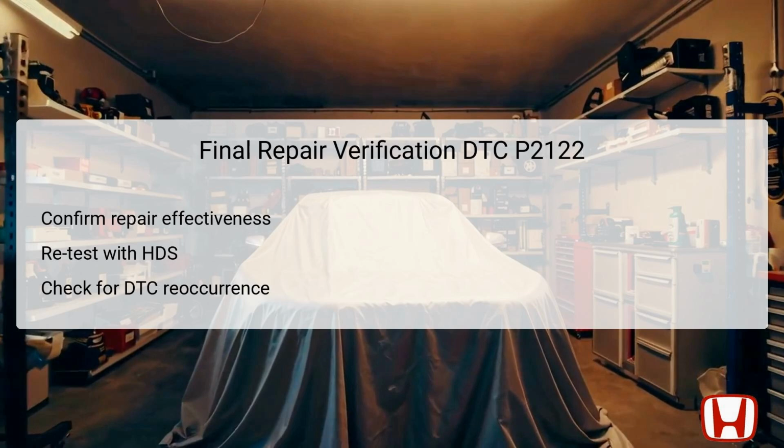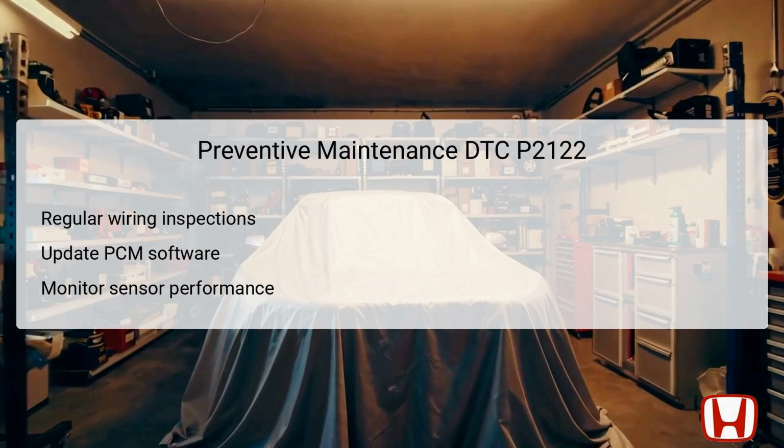A successful follow-up test confirms that repair work has effectively addressed the low voltage issue present in the APP sensor circuit, leading to optimized vehicle performance and stability. To prevent the recurrence of DTC P2122 and related issues, engaging in regular preventive maintenance practices is essential. One of the most effective methods is to routinely inspect wiring and connectors related to the APP sensor and PCM for signs of wear, corrosion, or loose connections, as these can lead to faults that might trigger diagnostic trouble codes.